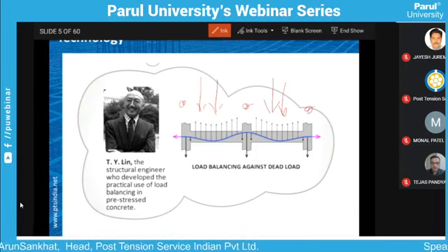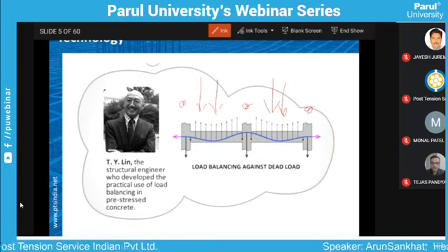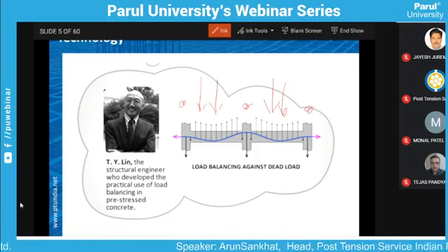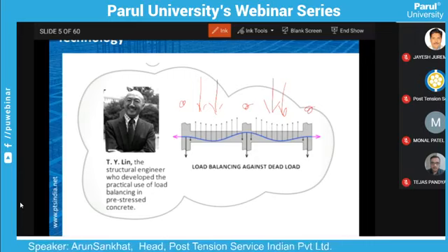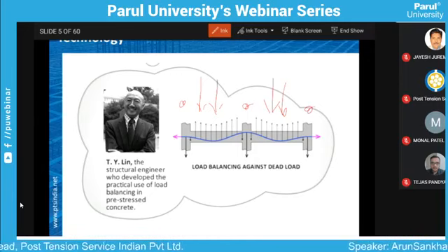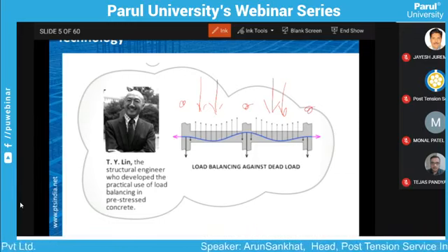These gravity forces will induce internal stresses, as we saw in the earlier slides on the basics of bending, or moment consideration, wherein you have tension at the bottom and compression at the top at the mid-span portion of a beam. Similarly, these are the forces that are responsible for generating those kinds of stresses in the beam.